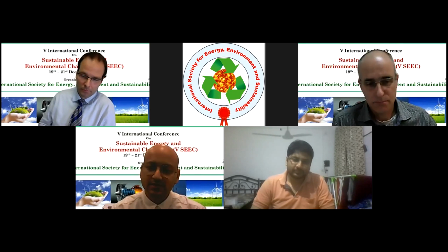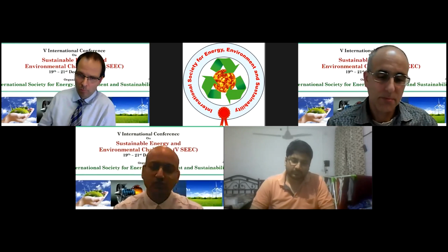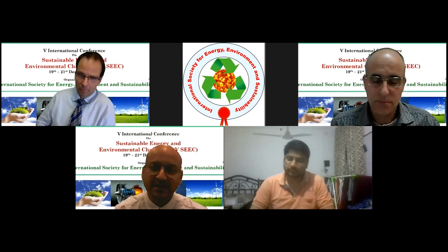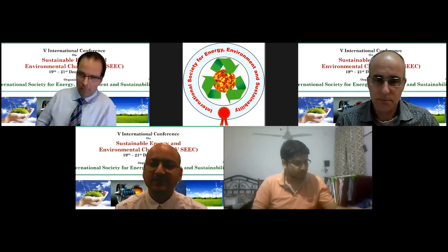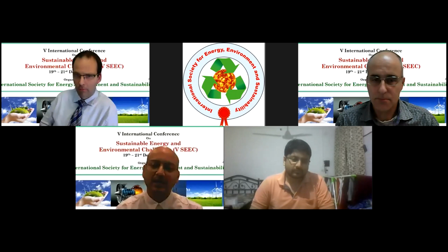So I agree with all of you, and that's why there was one question we, because of the time, were not able to take. Like, what is the main role of microbiology in membrane technology? So there are these MBR systems, which are replacing the activated sludge process in wastewater treatment, where we are trying to integrate the microbial degradation along with the membrane, and we are able to get fruitful results.